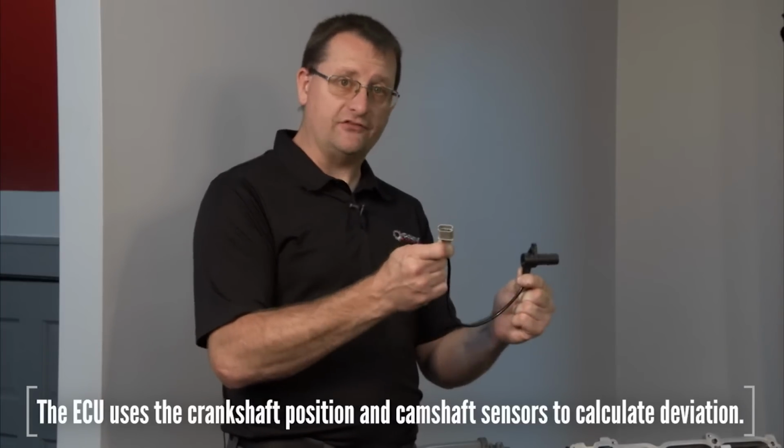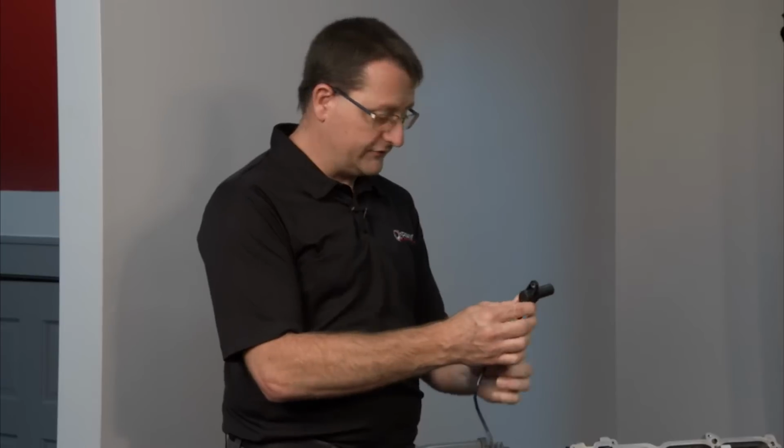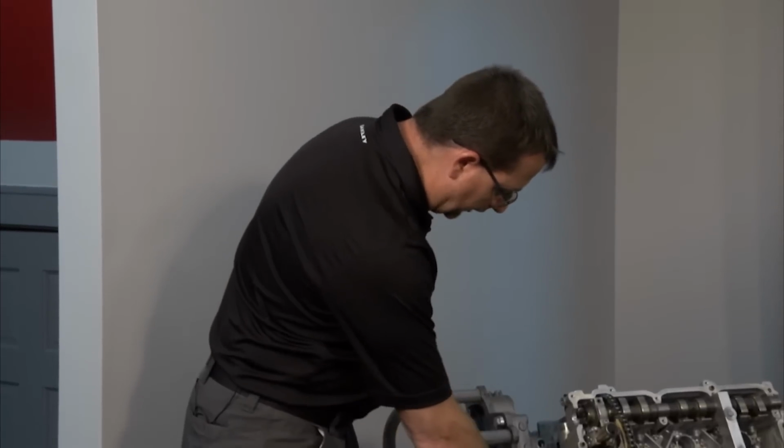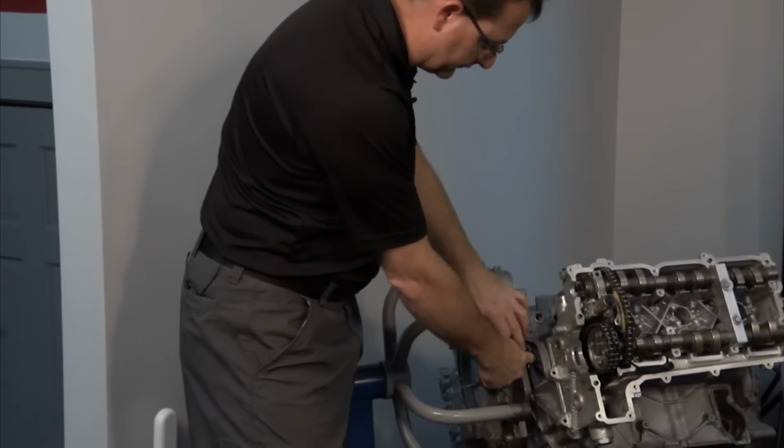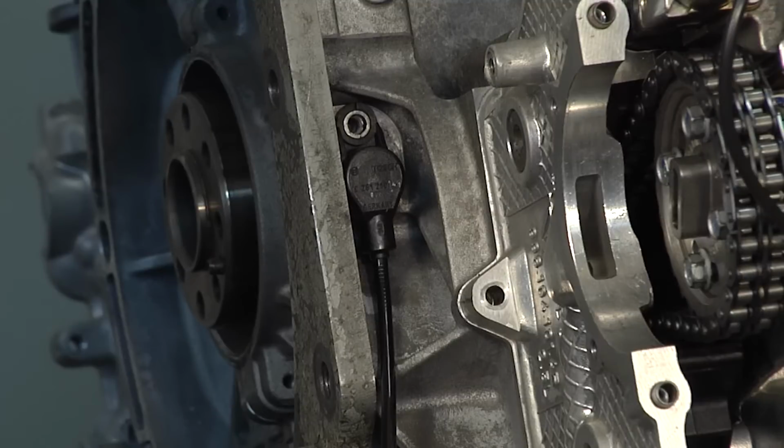So basically this sensor notices at what position the crankshaft is, and the 2 cam position sensors look to a reluctor wheel on each intake camshaft to report the position of the camshafts. Now this sensor is installed here in the crankcase. It looks to the flywheel inside the bell housing of the transmission for its reference point. These crankshaft position sensors are getting old and they're being responsible for reliability problems.